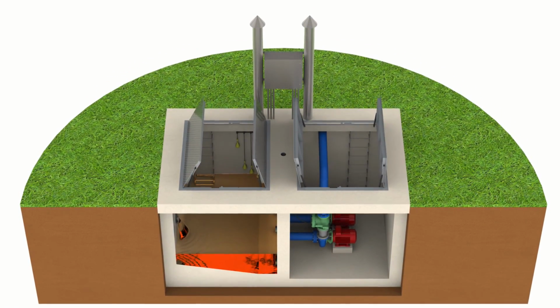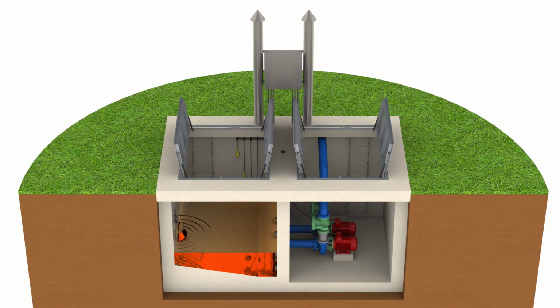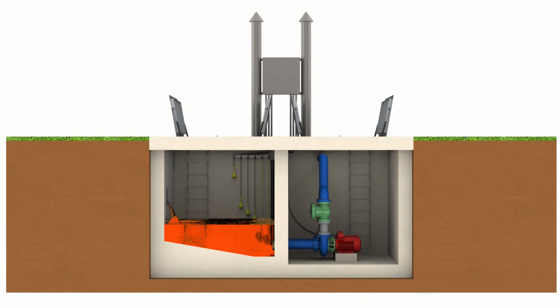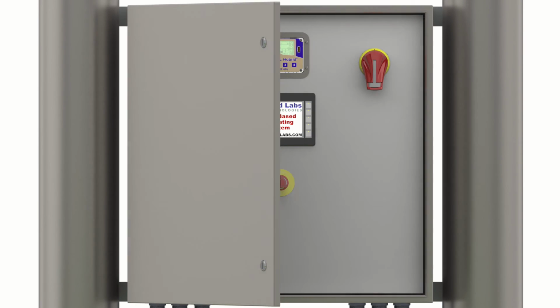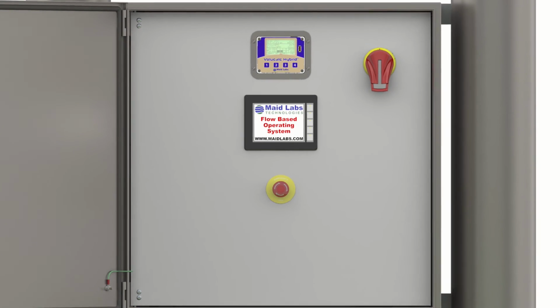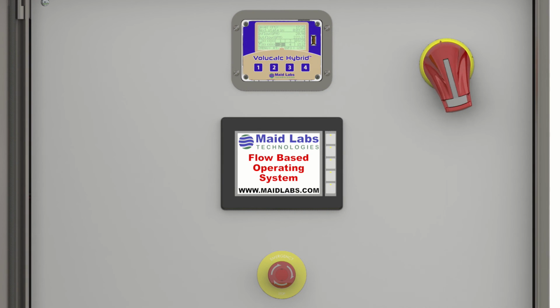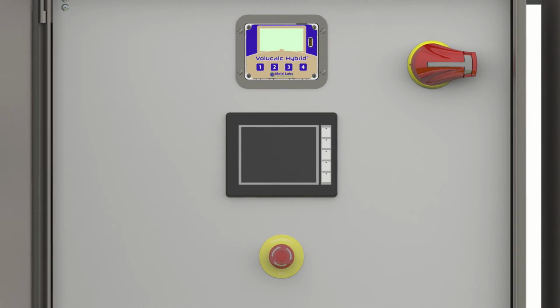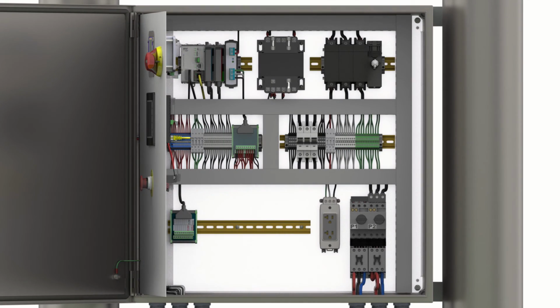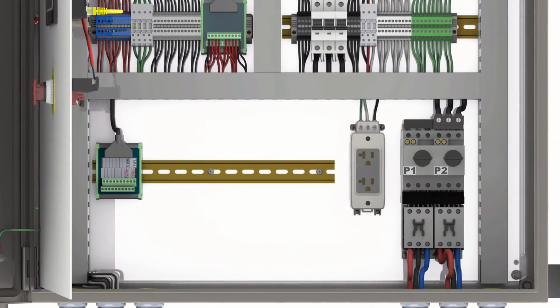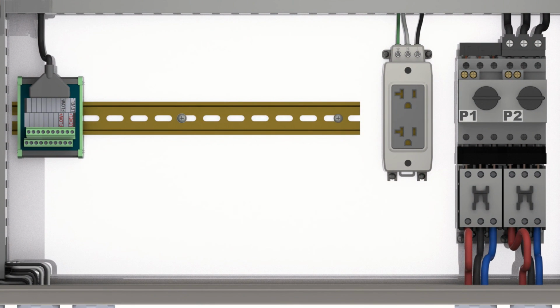In a lift station, when pumps start and stop, of course they are using current, which is proportional to the size of the pumps. With current, you know when the pumps start, you know when the pumps stop, you know how much electricity they are using. When the current starts, that means the pump starts. When the current stops, the pump stops. If you know the volume between the start and stop level, you know the volumetric flow in and out of that lift station. If you add the level sensor, then you will just check the level when the pump starts and when the pump stops, and you will be able to calculate flow rate.